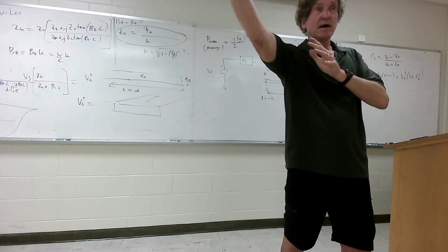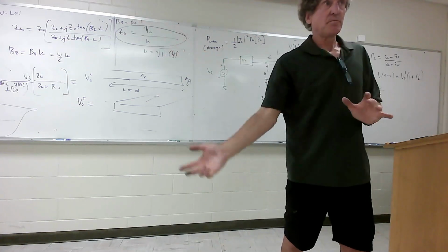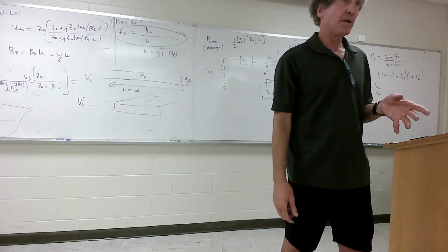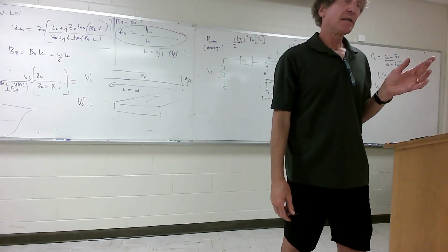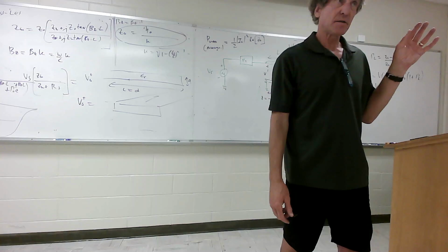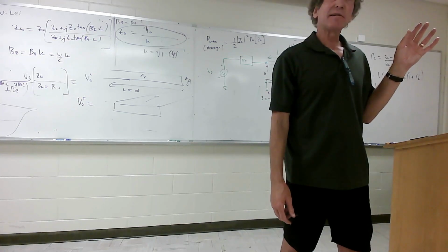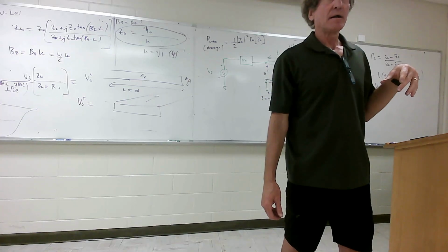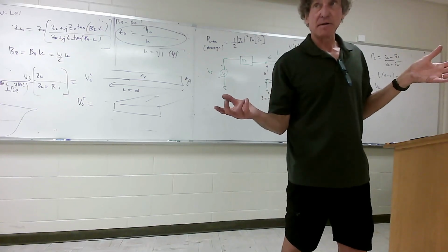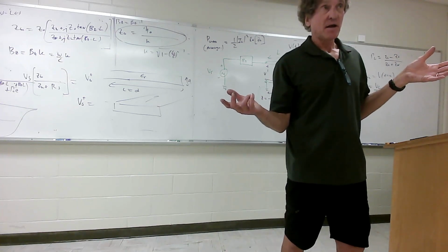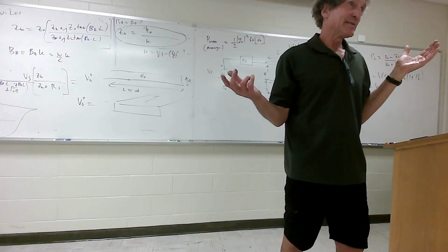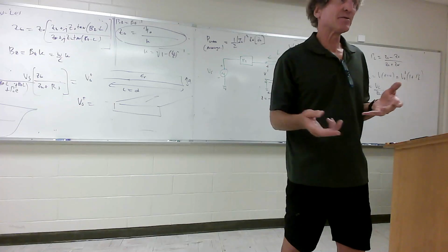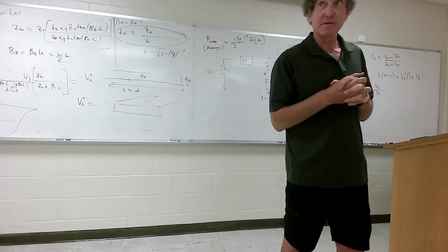They have it on a giant spool, and they unroll it very carefully and put it in the ground, and it can handle phenomenal amounts of information. And the attenuation, the rate that signal decays, is literally like a couple of dB per 20, 30 kilometers, almost nothing. Coax cable is like 4.5 dB per 100 feet. It's ridiculous, and that's just at a low frequency.